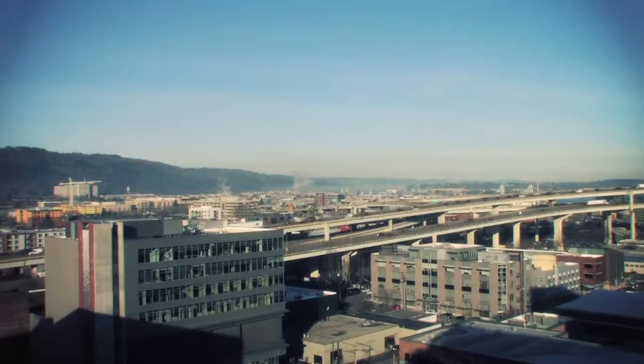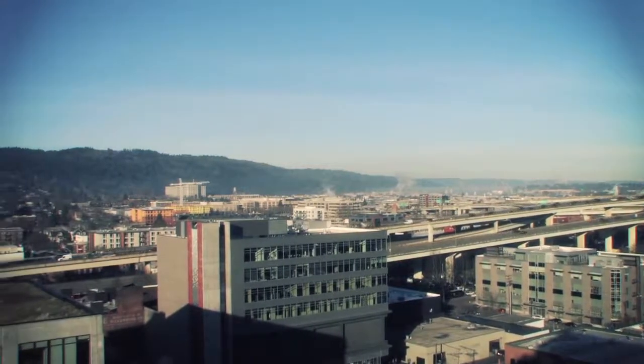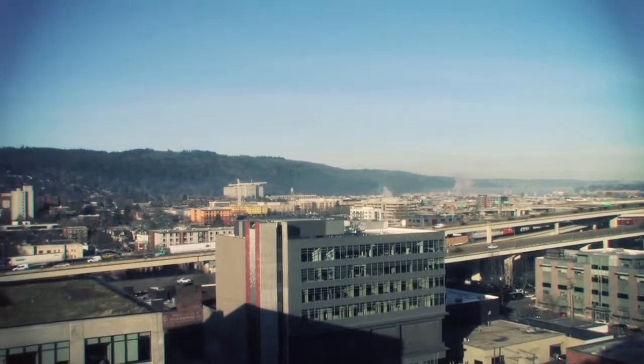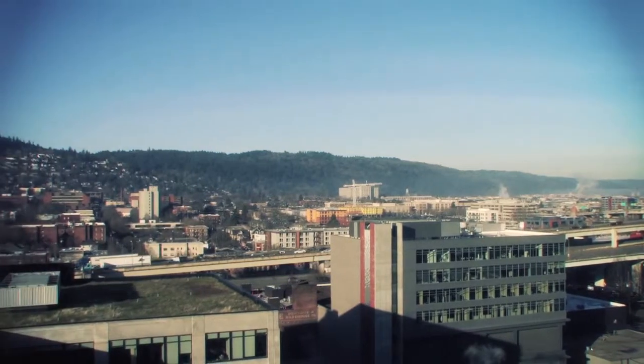We also have things like utilities underground. We're often doing retrofitting where we're working in environments that have already been developed, and so we have to work around the other infrastructure that's already in place. So things like water lines, gas lines, power, communications are all sitting there underground and make it a challenge sometimes to fit things in. We also have to look at other site conditions, slopes, how close we might be to a building. Contamination under the ground, if we're working in an industrial area, for instance, are all factors that we have to consider when we're working with green infrastructure facilities.